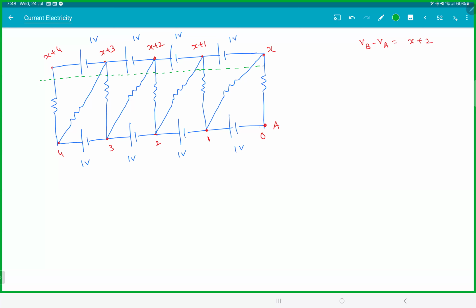Look at this green line. If I take this green line here, I will say this is I1, I2, I3, I4, I5, I6, I7, I8, I9. What can you tell about all these currents? The total current crossing this green line should be 0, isn't it? Because think about it, if you say I1 plus I2 plus up to I9 is not 0, that means...